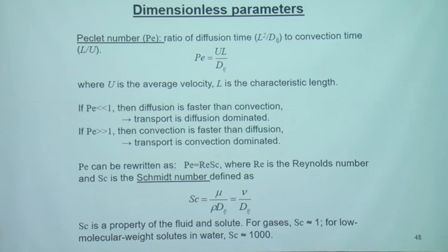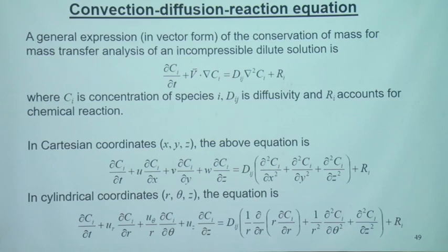What I usually teach my students, this is part of the course I teach to final year, fourth year MEng students at Imperial in chemical engineering, and also master's students: when I teach the mass transport part, I always ask them, before they solve the problem, to estimate the Péclet number and try to understand the dominant mass transfer mechanisms in the system, to decide whether it's diffusion-driven or convection-driven. This can help them to simplify the problem.